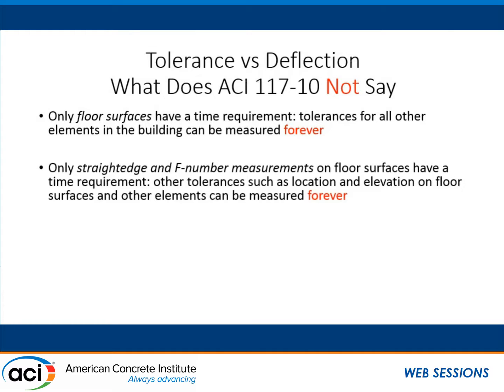Also, we've got a problem. We say we are not going to measure the elevation of a suspended slab because of deflection, but we don't have that same requirement for slab on ground. So if the slab on ground curls, we don't like it because that affects floor flatness and levelness, and we say, no, you can't do that. But then somebody who's smart enough reads and says, I can measure the elevation at the corners and come back at you again. So it'd be nice if we kind of handled that one too.